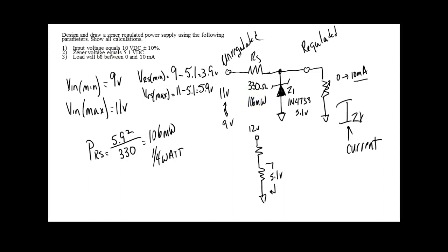Of course, I don't think I asked y'all to choose a wattage resistor. But we'd use a quarter watt. Everybody understand that? Yes or no? Because normally what we do is we double this, and then we choose the next standard value, and we would always round up.